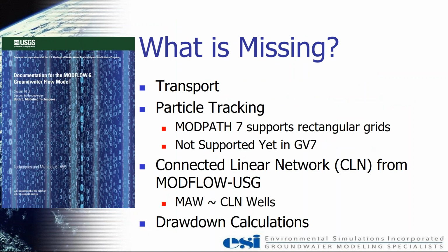So that's the basics. That's what MODFLOW6 does. That's what Vistas supports and what it doesn't support. So what are the other things that are missing? And I think the 2 main things are at the top here. The transport is not supported yet, and particle tracking is sort of supported, but not in Groundwater Vistas.